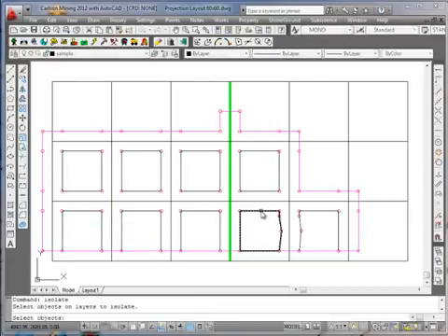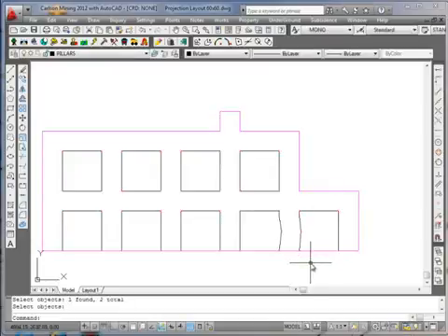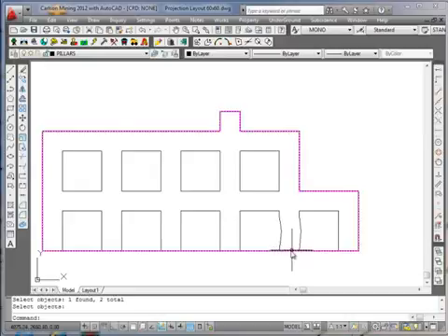So if I isolate to the pillars and the perim layer, that'll give you an indication of what we've drawn in terms of the mine map. The reason for showing you this area here is, this is the whole idea of drawing the offsets: as you advance down the center line, if these entries get off in any way, you're able to document exactly where the rib lines are.